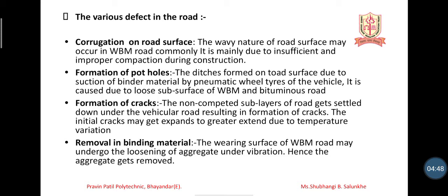Why are potholes generally generated? Because the binding material loses its adhesion property. If the binding material loses adhesion property, obviously the material will come out of that place. If material starts coming out of that place, then obviously a pothole is going to be generated in that area. Then the next is the formation of cracks. The non-compacted sublayer of the road gets settled down during vehicular load, resulting in the formation of cracks.